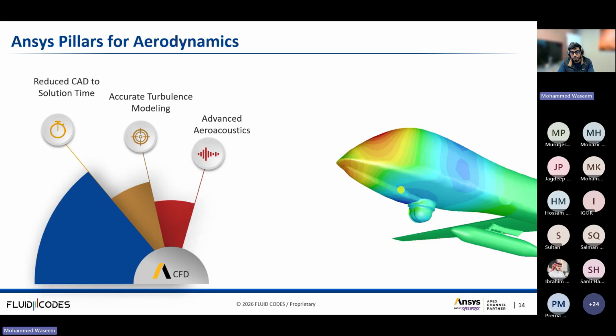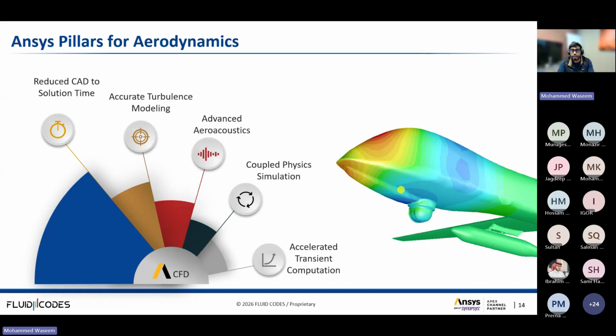In a couple of slides, we have a case we can talk about more. And then we can couple CFD along with structures to check wing flexibility and aeroelastic risks such as flutter. For maneuvers, gusts, and propeller interaction, we run transient simulations in order to capture those peak loads. With this, let's talk about the aerodynamics workflow in the next slide.